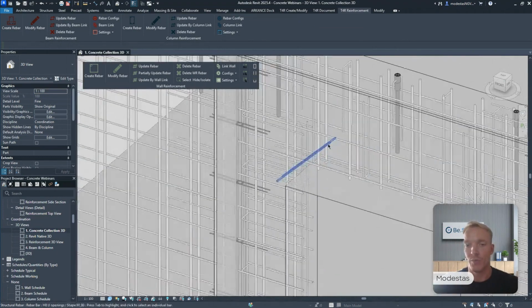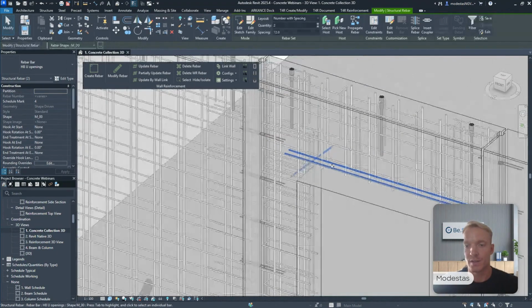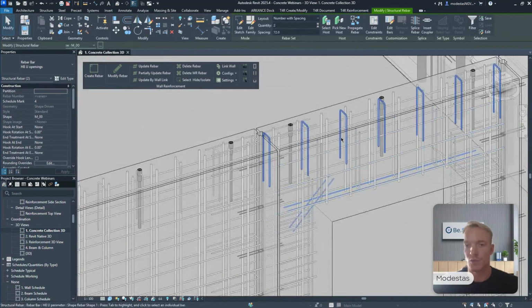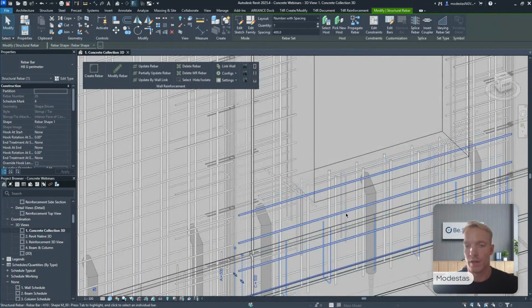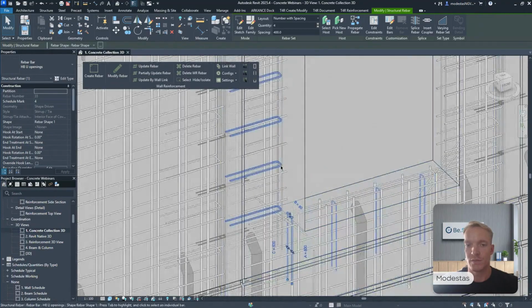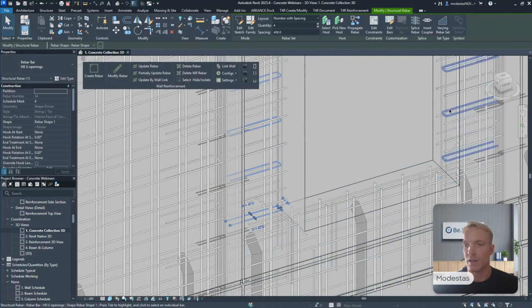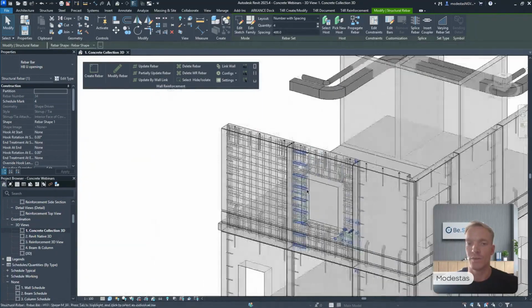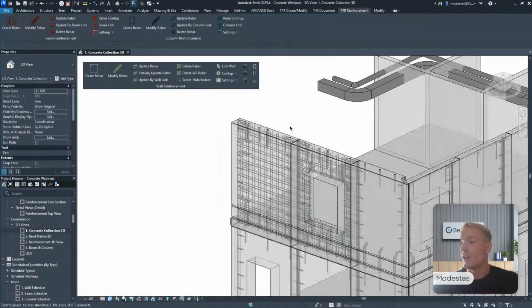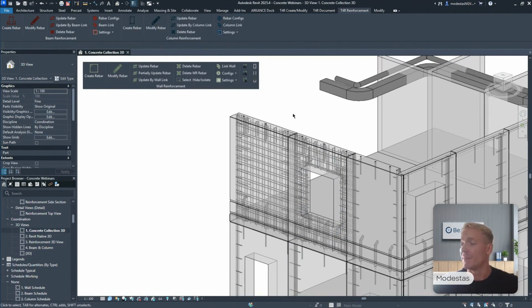I have the opening reinforcement bars placed properly over here. I have some U-shapes at the top and bottom of the wall panel. I have those opening U-shapes from the sides, and all of that is being done automatically for me. So I can create one configuration and reuse it. It doesn't matter if there are some geometrical changes or not. And the best part is the adaptability, right?